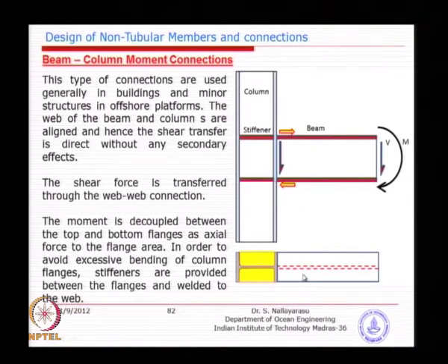Otherwise, what will happen? When the force is transferred, this flange will start rotating. So, unless you connect the two flanges by this stiffener and make sure that the load is transferred to the web because of shear, that is the idea behind it. So, you need to design these stiffeners, which you can do with a simple basic mechanics calculation by transferring shear. You can take 50 or 40% of the stress that each stiffener will be able to take.